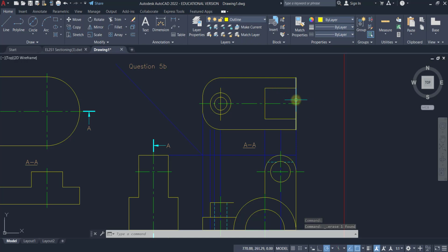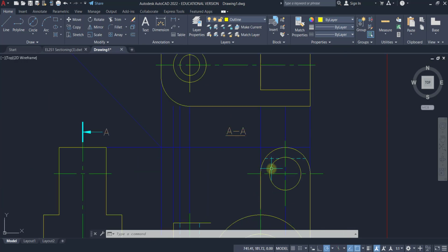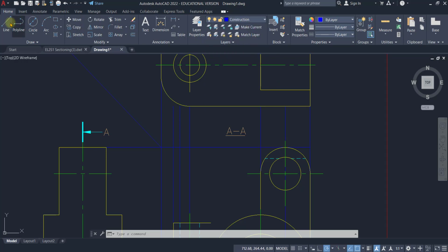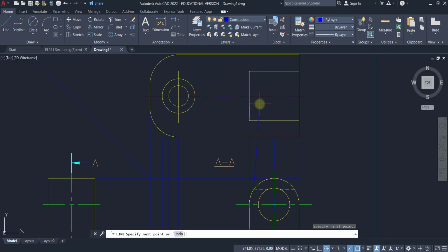Next thing is the 12 mm opening. Alright, for the 12 mm opening, you need to track from the feature from the front view. Okay, so go to here, I need to go to construction line. From this point, track it upwards. Alright, so from here to here, you notice that the opening is not going to be very big, or rather the rectangle is not that big. It's going to be confined by the length of the hidden line. Okay, alright, so it's going to be 12 mm.